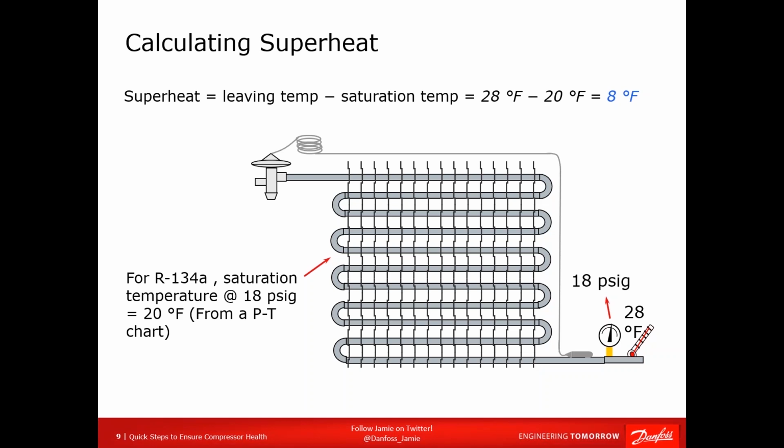That means the refrigerant is changing state at 20 degrees, going from a liquid to a vapor. Now, eventually, you're going to run out somewhere in here of liquid. You're going to hit the dry spot on the evaporator where you no longer have liquid, you only have vapor. And this vapor, because it's colder than the surrounding air, is going to continue to absorb heat.